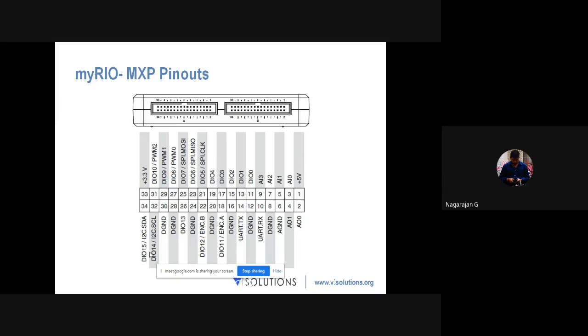Okay, at the same time, this hardware will support protocol based sensors. Okay, so we know that some of the hardwares will work with respect to some protocols. For example, we have CAN protocol. We have serial communication protocols like I2C, and then you have SPI protocols, serial peripheral interface. You have UART. So whenever you have such type of sensors which work with respect to a protocol in order to have a data transfer, this hardware will support I2C protocol, SPI protocol, and then UART.